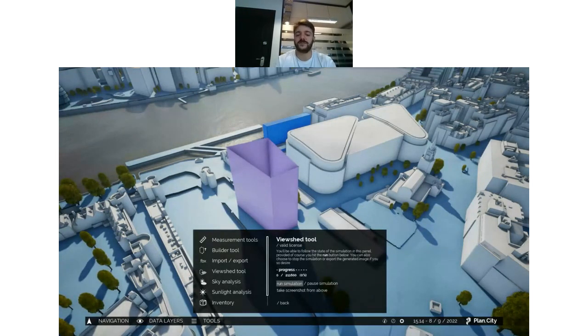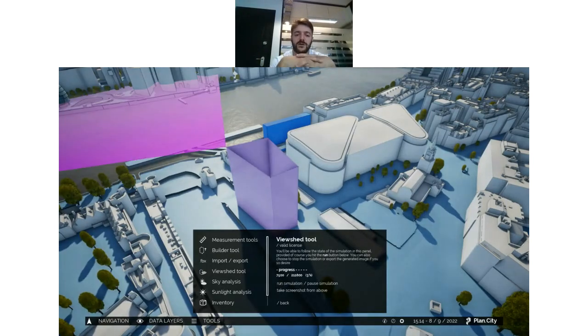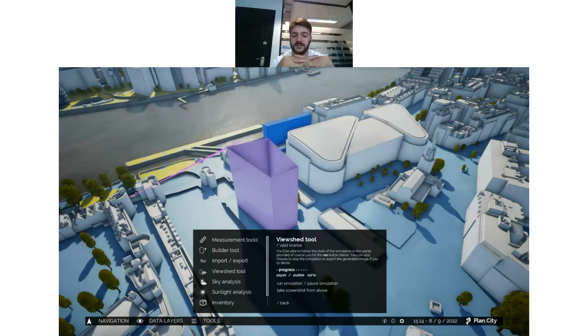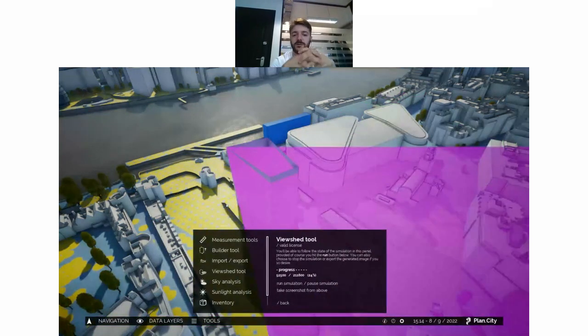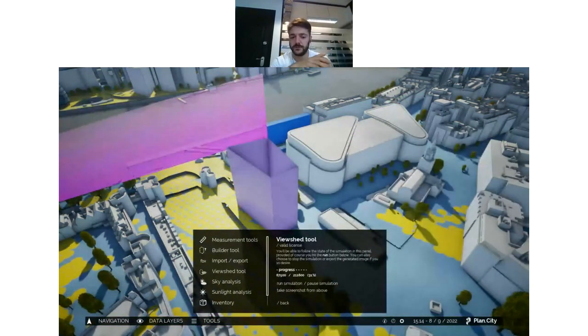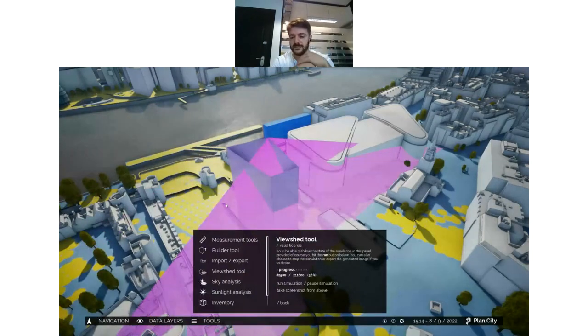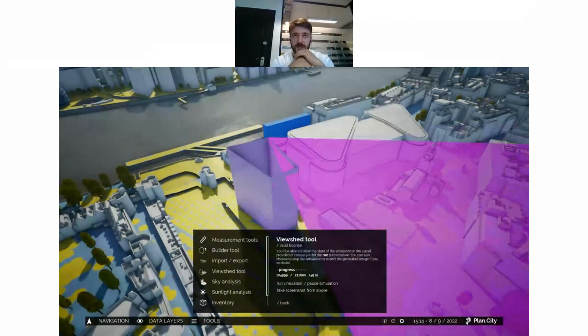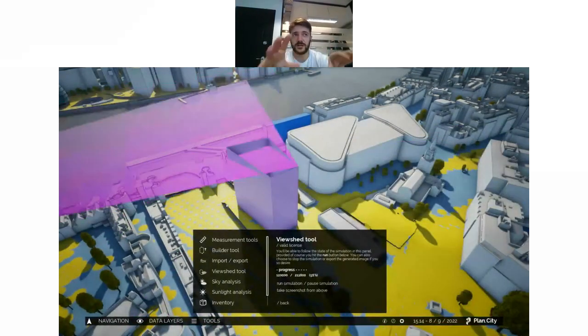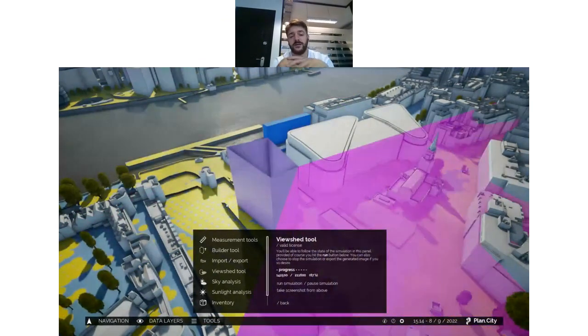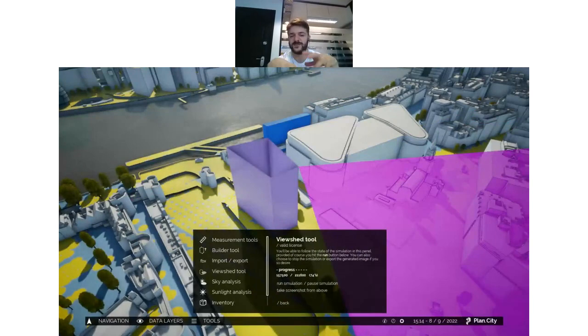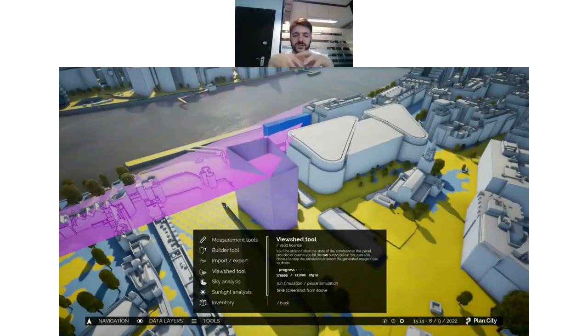As you'll see in a moment, this will paint in yellow the areas from which this building is visible, and it will leave in blue the areas where we can't see the building from, according to those settings that we've used before. So we are conducting the analysis over an area 1,300 meters away from the building, and with a spacing of 6 meters between each of the analyzed points.